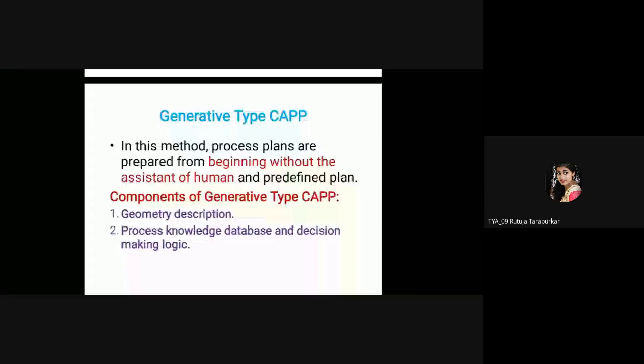It involves all the geometric features for all the processes related to the surface, together with dimension, location, tolerance and surface finish. Okay, the first component, geometric description, will include all the geometry-related information, meaning dimension, location, tolerance and surface finish. Those things will come under this first type.